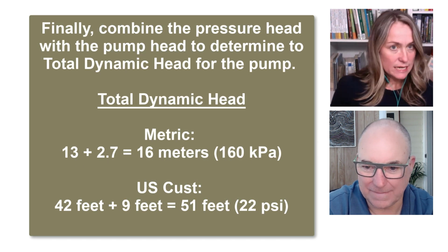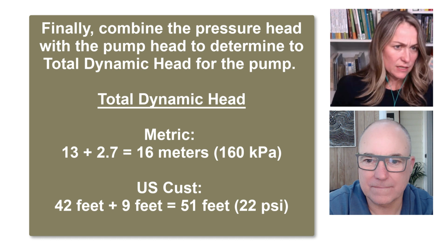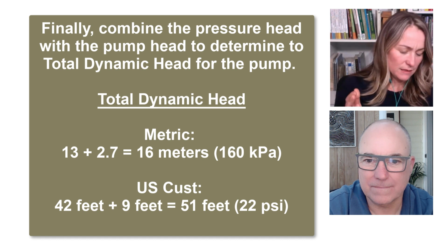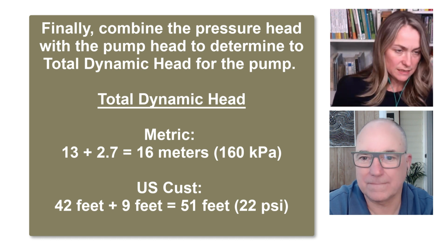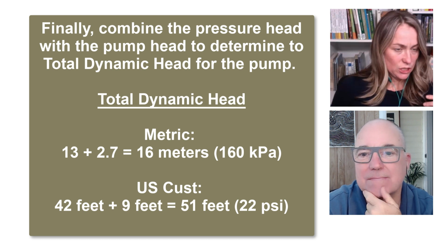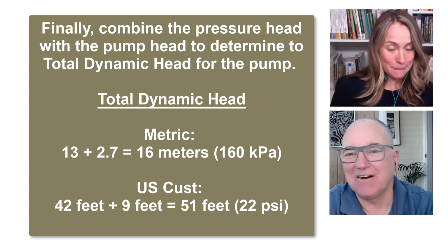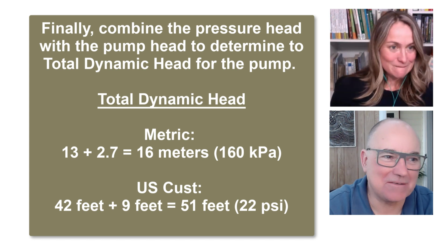So I will take 27 kPa or 4 psi. We're going to convert that. You can do it in kPa, psi, or meters or feet. So it depends ultimately on which units you need for your pump curve. We'll get there in a minute. 9 feet or 2.7 meters.